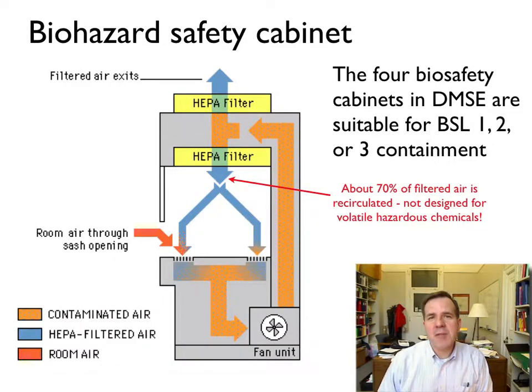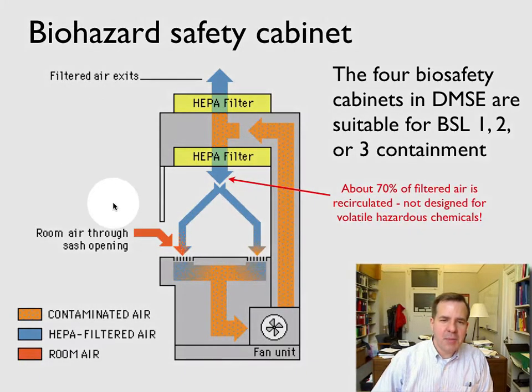And the most important item of equipment in this regard is the biohazard safety cabinet, which is shown here. This is in cross-section. There's a sash here. Here is the interior of the cabinet itself. The person working would be standing sort of out here. Air is drawn from the cabinet down through a fan. It's then recirculated up to the top in this particular schematic, where it is then divided into 2 streams.